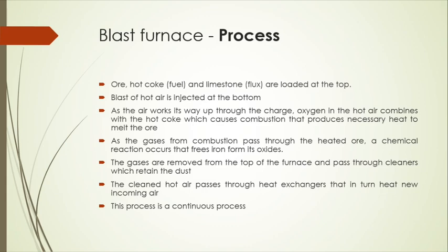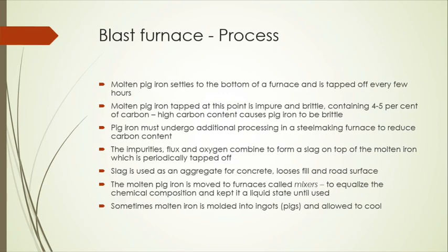and then heats up the ore, and a chemical reaction occurs due to the heat. The impurities combine with the flux, and the flux will float at the top, which you can separate from the pure iron. The molten pig iron, which is the pure iron, settles to the bottom of the furnace and is tapped off every few hours. So you collect the pure pig iron every few hours.